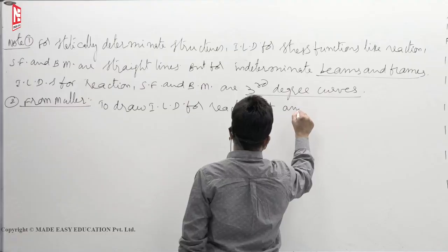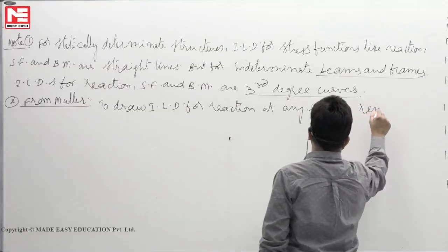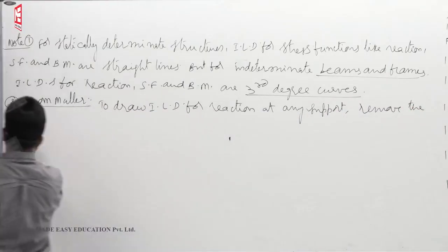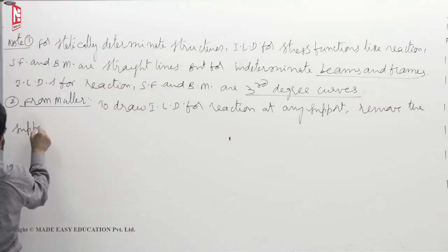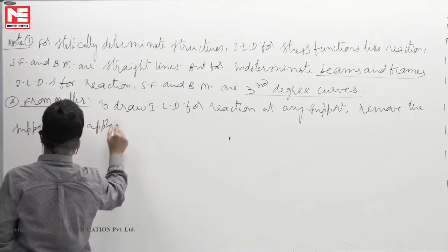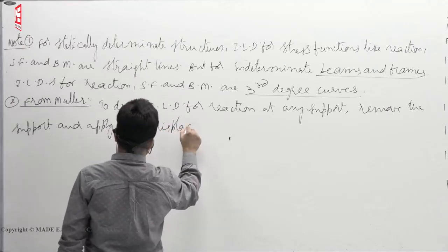To draw the ILD for reaction at any support, remove the support and apply unit displacement.